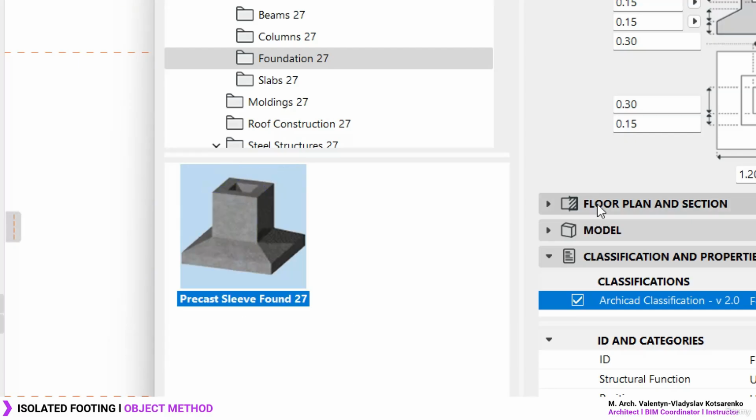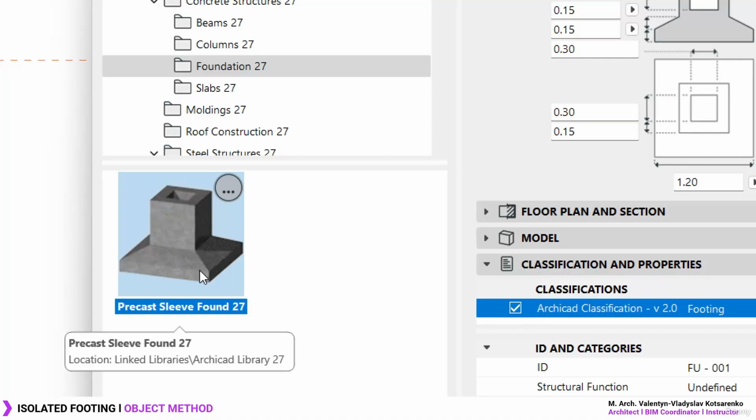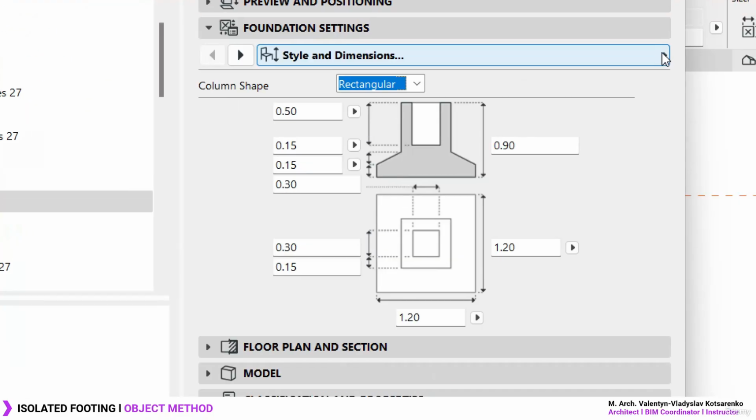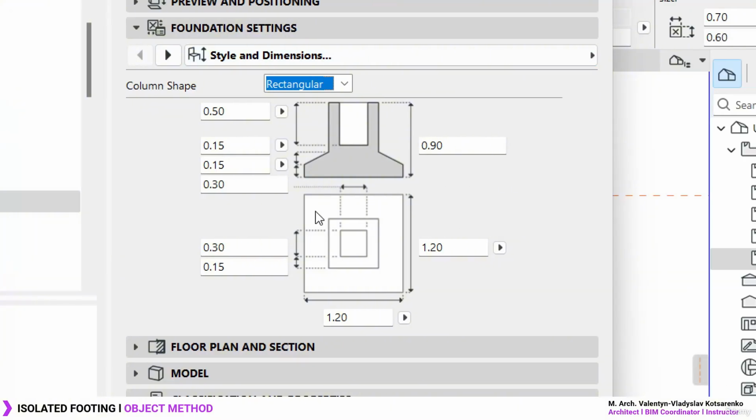You can simulate, or you can delete, in quotation marks, the hole within the foundation. In really easy steps, you can simply set this to be 0 and set this to be also 0. This is where you can specify the dimension of the hole, the width and the depth over here.